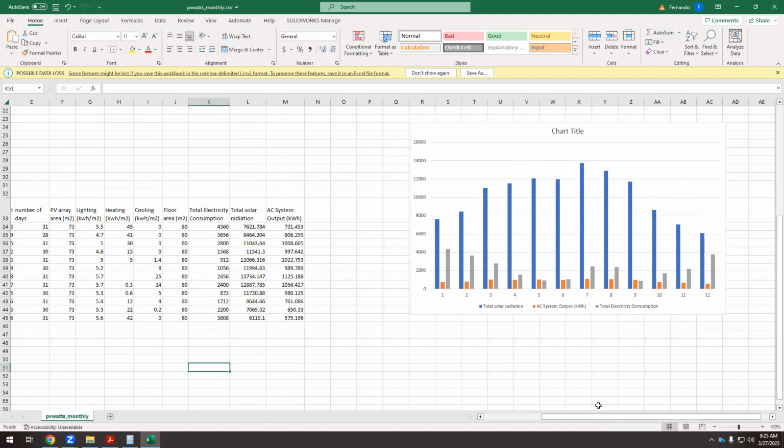So this is the result. Are we far from the zero energy building? We are far from the zero energy building, but believe me, if it weren't for all the measurements that we have taken, the high R value, solving thermal breaches, using triple glazing, providing the building with shading devices, we would be even farther. Okay, so at least there are some months in which we can get the zero energy building.